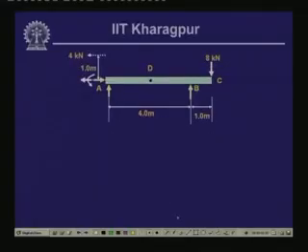So, if we take the free body of the whole beam, this looks like this, that the 4 kilonewton load which was acting at a distance of 1 meter from this support is now transformed to this place where we have a horizontal force of magnitude 4 kilonewton and the moment is 4 kilonewton meter, because 4 times 1 will give you 4 kilonewton meter as the moment.